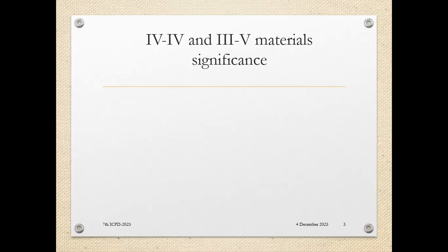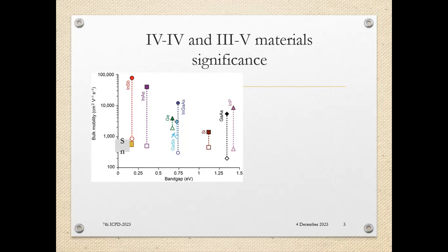So we are going to describe the significance of the high band gap silicon germanium nanocrystalline materials for transparent photo device applications. Normally, lower band gap materials have higher bulk mobility or carrier transport properties, which eventually makes them successful for better optoelectronics and electronic device applications.